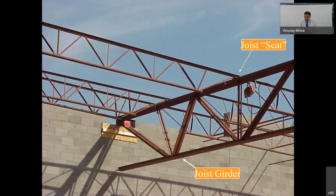So these are some of the examples of the open web sections where you have different kinds of trusses, and so they are making the structure lighter, but all the time they are obviously taking more time to fabricate, and all the time you may not like, from the aesthetic reasons as well, to use them in these structures.